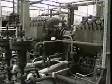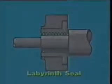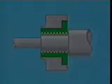The most common types of seals are the labyrinth, liquid film, carbon ring, and mechanical. The simplest type of seal is the labyrinth seal. It has a series of grooves machined to sharp knife-edge thickness that maintain a close clearance to the mating part. It can either be stationary or rotating. The mating parts are made of a softer material such as babbitt, so they will wear before the labyrinth does. Labyrinth seals can be found in multiple, step, and interlocking configurations. Sometimes carbon rings are included with the labyrinth seal.